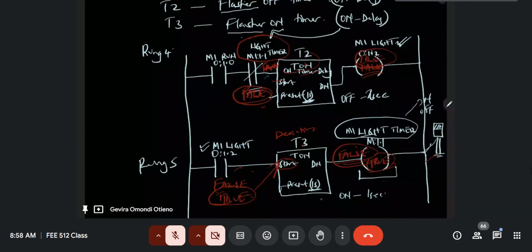Yes. Because this is an on delay timer, as long as it is active, it only delays the time the light takes to come on, let's say now for T3, the light stays on. So even if the previous case, remember, as soon as you activate or start T3, it will start counting. The only reason it will stop the count and change the state of the output is if power goes off, or if suddenly somebody shuts it down.